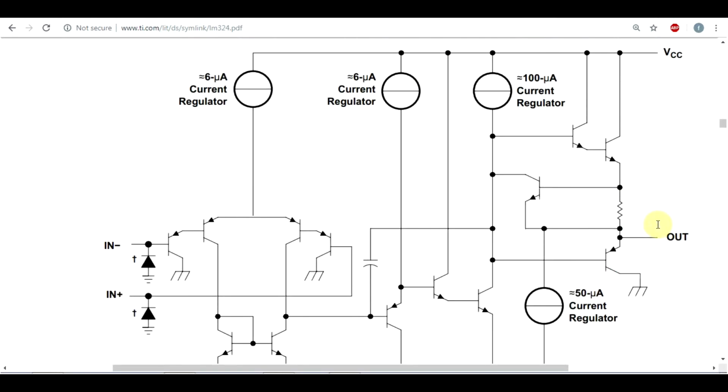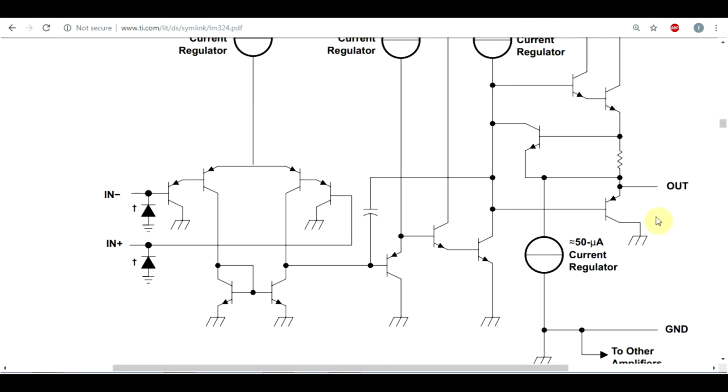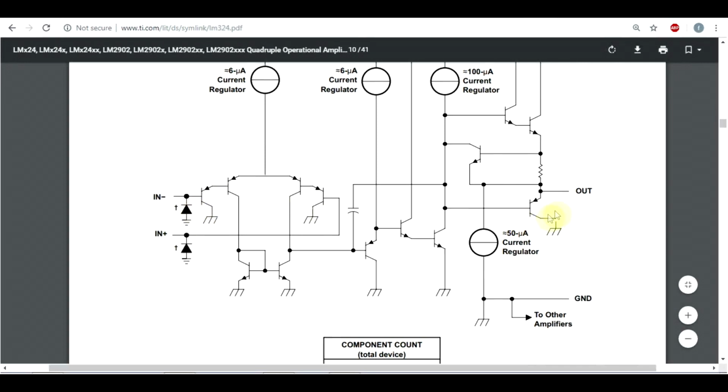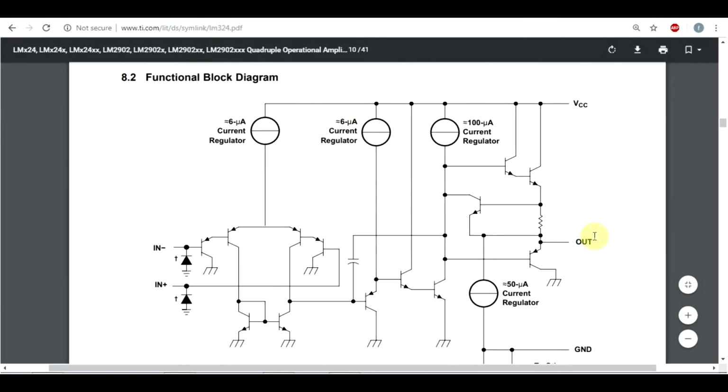So all in all, when choosing an OpAmp for your circuit, depending on what you want to do with it, you will always need to take into consideration not just the input limitations, but also the output limitations. Just because you're supplying the OpAmp with a certain voltage doesn't mean that the OpAmp can actually handle that voltage on the inputs and the outputs. This will be especially important when designing circuits with very low supply voltages.